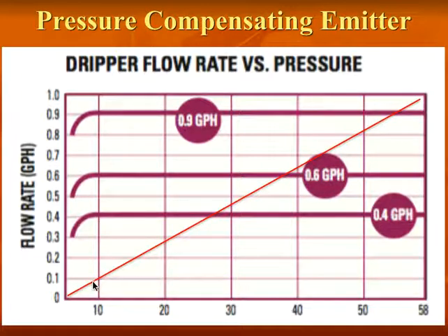Now this is in relation to the results of a non-pressure compensating emitter, shown by this red line. Non-pressure compensating means that as the pressure in that tubing increases, the flow rate also goes up. And this can be somewhat problematic in doing designs and trying to match lateral lengths with inlet pressure. The pressure compensating emitters just make designing so much easier and so much more simple.